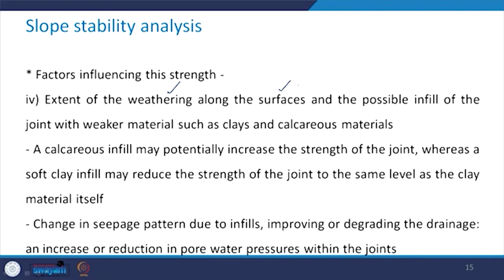If the infill is a calcareous one, it may potentially increase the strength of the joint, whereas in case of soft clay as infill, the strength of the joint will be reduced to the same level as the clay material itself, because it will be the soft clay infill which will govern the strength characteristic of the